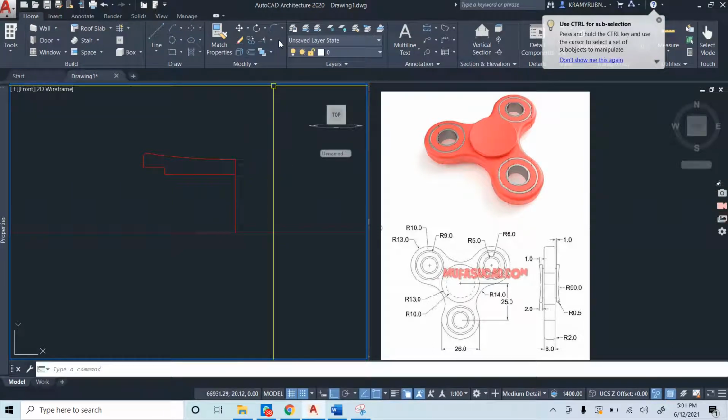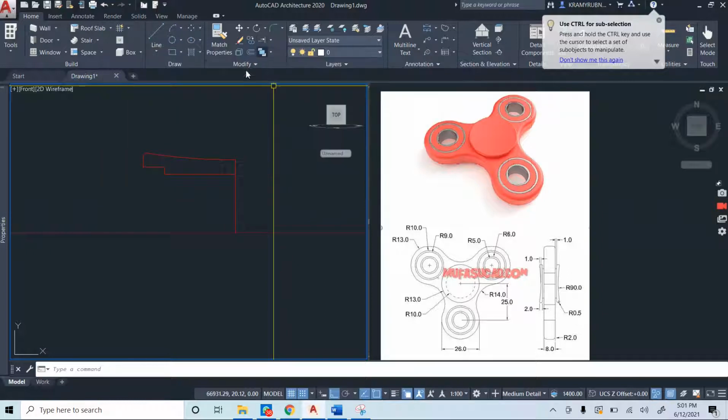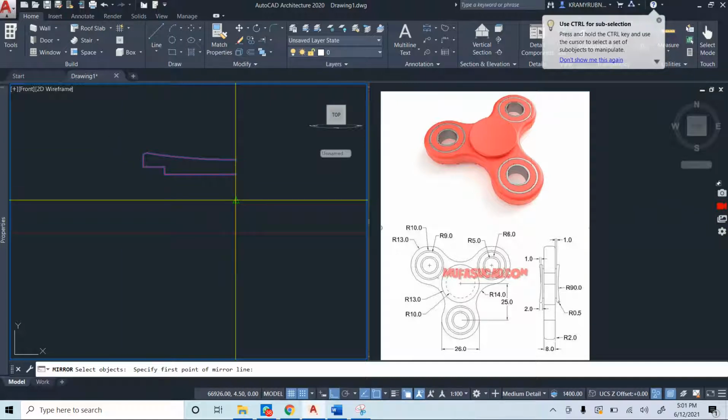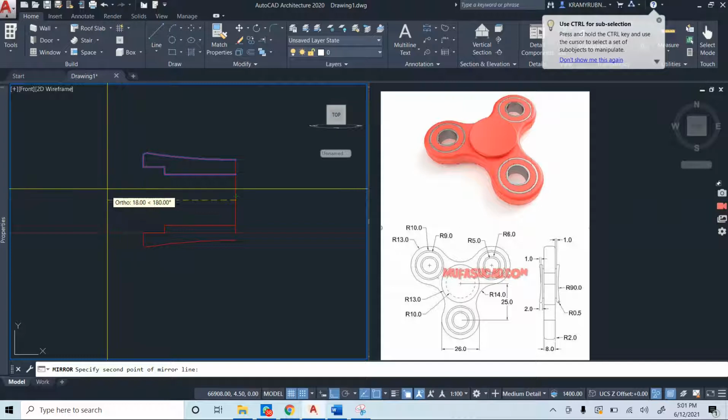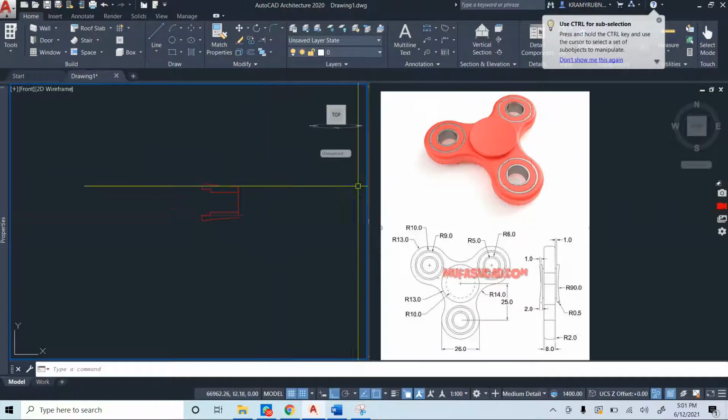and let us also mirror that. So mirror, here's my mirror, and I wish to mirror this entire shape, and I want it in the halfway, like that. And we're basically now just going to give revolve command.